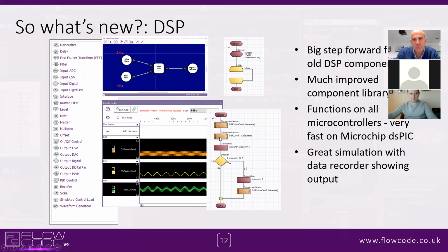It's a 10 kilohertz interrupt. Add the 2 values together. If you've counted to 10, then generate the next value for the next one. So it's a dead simple way of having a 10 kilohertz and a 1 kilohertz signal generator, and then adding the 2 together, and you could have then an output which is digital or analog, whatever.